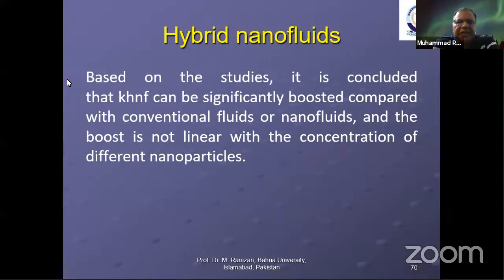Based on the studies, it is concluded that the thermal conductivity of the hybrid nanofluid can be significantly boosted compared with the conventional fluids or nanofluids, and the boost is not linear, but depends on the concentration of different particles. Hybrid nanofluid showed enhanced characteristics of the thermal conductivity in comparison to the conventional nanofluids. Adding hybrid nanoparticles can significantly enhance thermal conductivity of the base fluid.